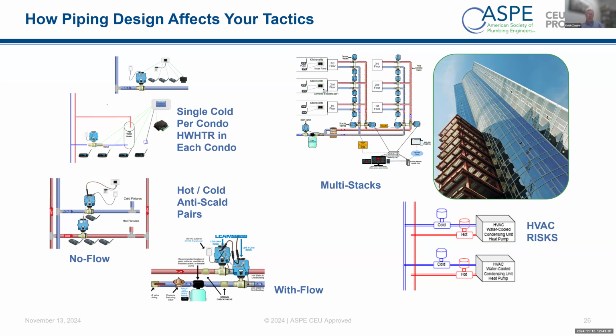So we can just put the valves down at the bottom of your risers. We can put the valves and the leak detection systems on all the branches. So really what we're seeing, if you want to know the trend across the United States, is a lot of the cities, jurisdictions and states are requiring metering of all multifamily or subtenant metering on the water side, knowing that the psychology of it is that when you meter, when you make the customer pay for their water, they use 20 to 30% less water. You'll hear that stat over and over. That's the reason they're making these things laws.